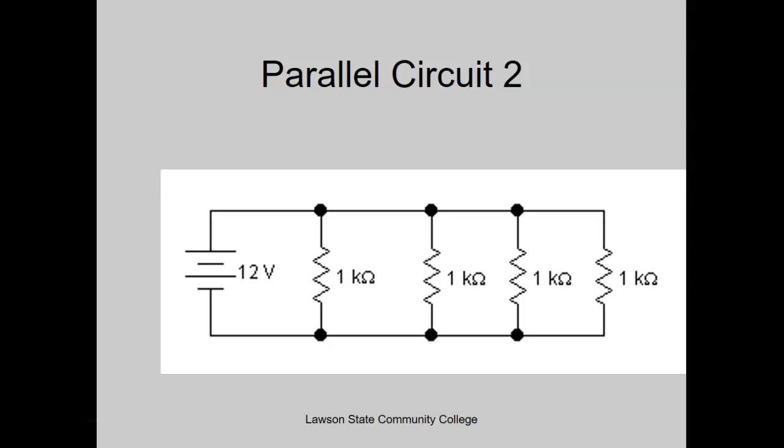When you add up 0.001, your overall conductance total is 0.004. If you take 0.004 and take it to the -1, what do you get? 250. That x to the -1 key, or the 1 over x key, whatever y'all have got. Okay? Like I said, it's not as painful as you think. This is a very fast, easy way to do this.